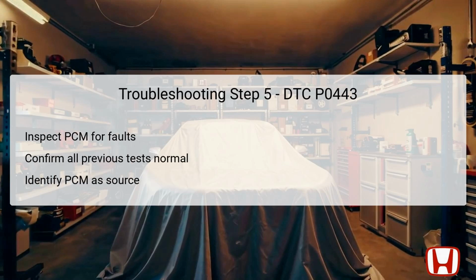The fifth and final step in troubleshooting DTC P0443 focuses on the PCM itself. If all prior inspections have yielded normal results, and if the Evap Canister Purge valve and associated circuits have been validated as functional, then the PCM may be the root cause of the malfunction.